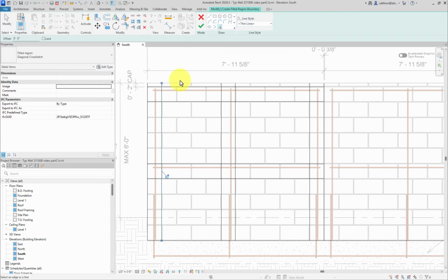So I've picked those lines, and so my choice is to split the element. There's 2 split tools here. I want to use the split, not the split with gap. So I'll click this. That allows me to break each of these somewhere in the middle here. And I'm also going to need to split these two horizontals right there in the middle. Come back with my corner tool, make all of my corners. And that's definitely faster than going and picking the lines again.